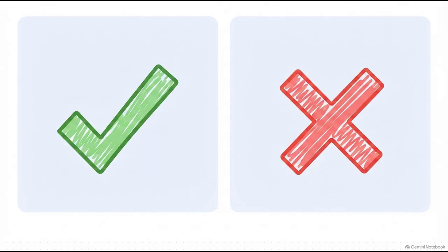When we're talking about cold weather, the line between good practice and bad practice is black and white. If it's 40 degrees Fahrenheit and rising, you're good to proceed. But your shotcrete material temp, when shot, has to be at least 50 degrees Fahrenheit. Now, if it hits 40 degrees and is falling, you must stop unless proper protection is provided. And the ultimate zero-tolerance bad practice, never, under any circumstances, place shotcrete against a frozen receiving surface.